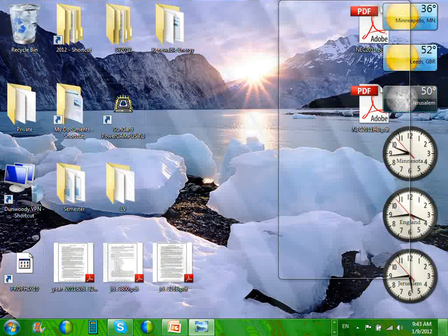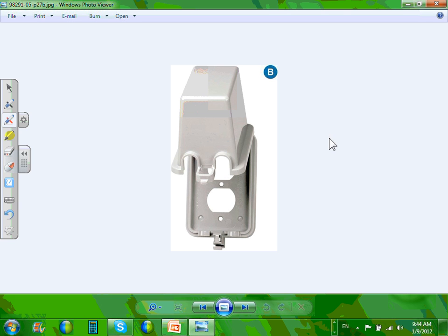So don't worry about that. But I would give it a dedicated circuit though. You're telling me that's 16 amps, Chad. If it's 16 amps, most likely if they put a 20 amp receptacle and plug on it, it is in reality 16 amps, but they want you to plug it into a 20 amp. They take into consideration the continuous load.